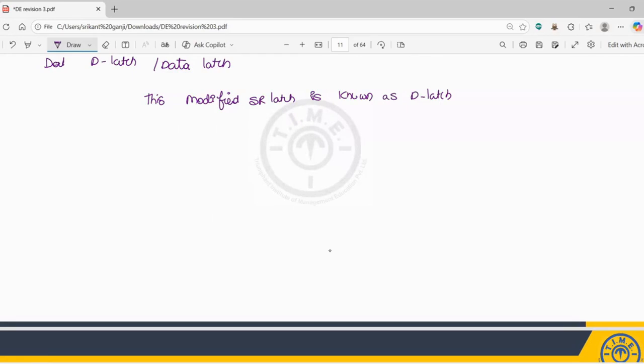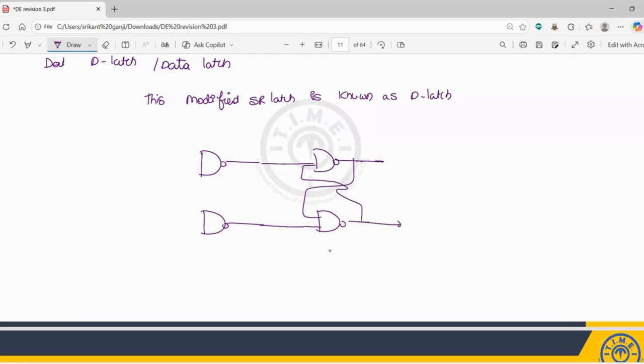Okay, the circuit won't change, only there is a small change here, and this is also D naught. This is the circuit. This output is given to here, and this output is given to here, and this state is Q, and this state is Q bar. Here it is set, here it is reset, and these two are enabled with the enable pin. Now the scenario comes into the picture. So D is given, and with the NAND gate, I can give it to this one, or I can give it to the reset.